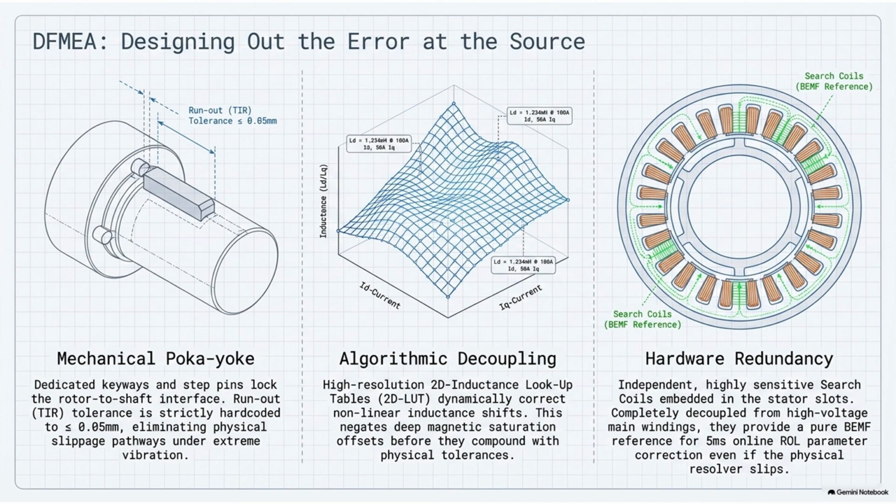The interface must have a dedicated, high-precision machined keyway or a geometric positioning step pin made of solid steel. So there's a physical metal groove on the motor and a solid steel pin on the sensor that slots tightly into it. Yeah. The resolver physically cannot rotate out of alignment unless the rotational vibration forces are strong enough to literally shear solid steel in half.